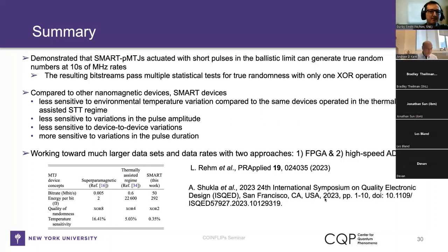Okay. We do have a question about SOT versus STT. Specifically, how do you anticipate the 3-terminal SOT device will limit the density of the devices, or is that not really an issue? Oh, that is an issue. The issue is that you likely need 2 transistors to operate the SOT, and you're likely to need more. So you're likely to need more area. You will need more area.